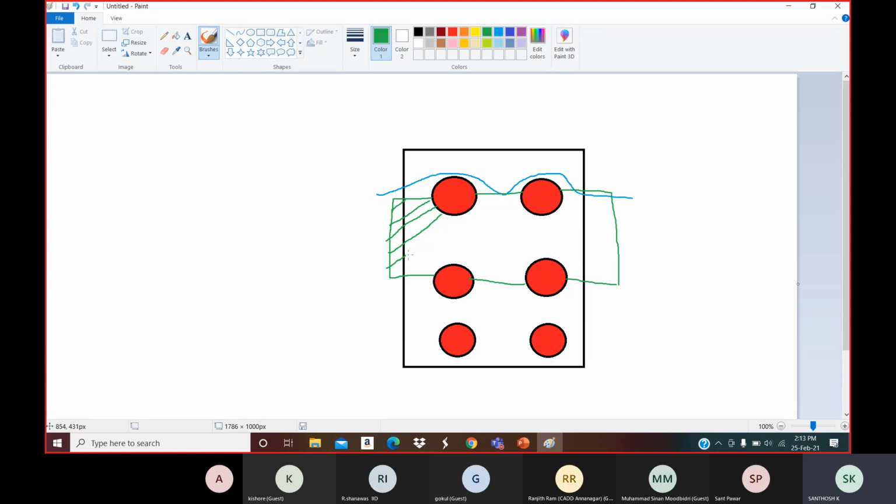Then, sir, what about the other tubes? What could the other tubes be? What I do is, from this area to this area, I'm going to mention this as an inlet, and this area is the outlet. This is inlet and this is outlet. Then what is the use of periodic? See, here also there is an inlet on the top, and here also there is an inlet. That's the reason we make that periodic. What do you mean by periodic? Periodic in the sense of continuous. So I'll mention from here to here is an inlet, and here to here is an outlet.